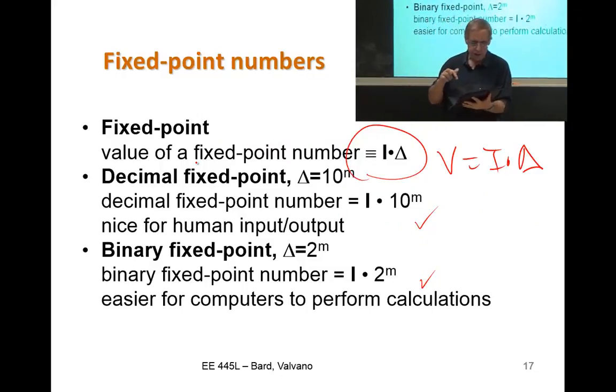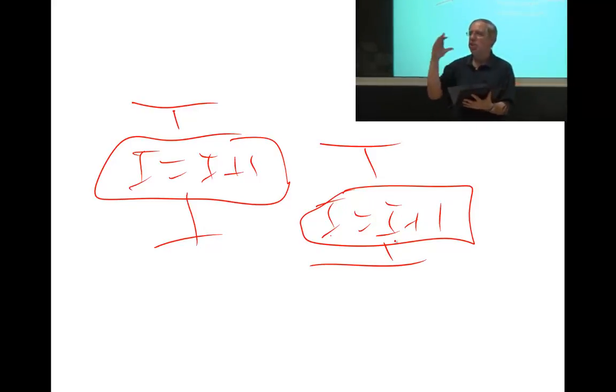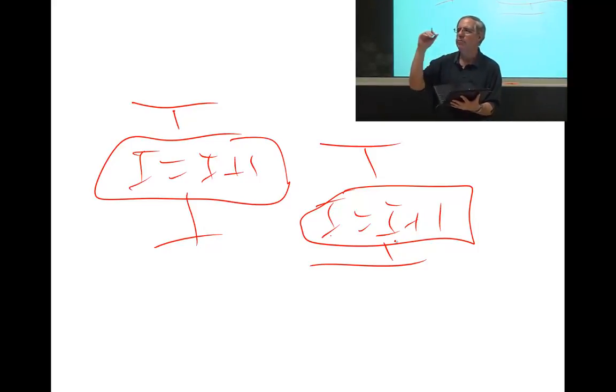We'll see this also in interrupt service routines, right? We're going to make it volatile because there's anything that's shared between the main program and an interrupt, anything between an interrupt and another interrupt, we'll make it volatile. All the I/O ports will be volatile. Good question. Any other questions?